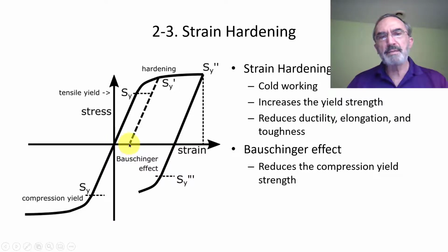And since there is permanent strain, that means that the structure is permanently deformed, all right? So this is what happens when you are in an accident with your car. Something gets bent this much in strain. Okay, and if there is a strain, there will be displacement and you will see it. So, okay, fine, so we have this. Then we can load again, but if you load again, you start here. You'll never go back to this point.